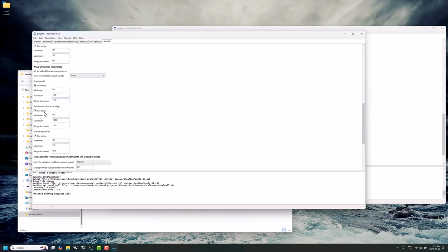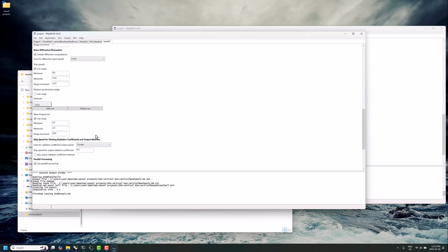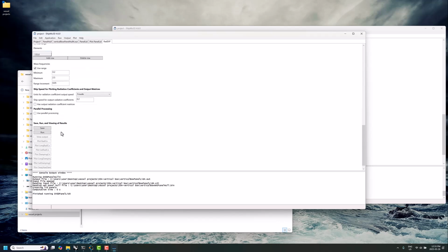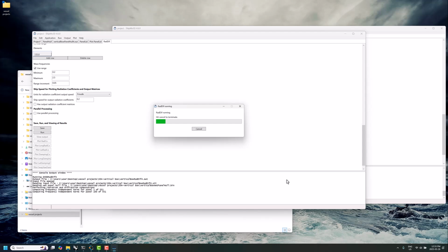Now, if you wanted to look at this, it covers a wide range of sea states. It is just one relative heading, bow quartering. If you wanted to look at specific case-by-case comparisons, this is the time to add in a few, or use the range, or maybe use a few different speeds and things like that. But for now, I just want to do a large yacht motion affected comfort rating. Turn off parallel processing, and let's let it run.